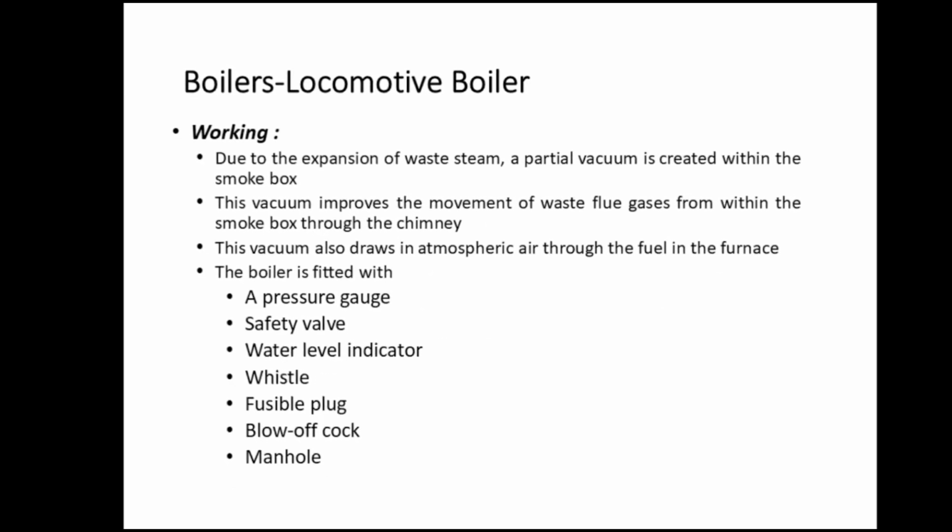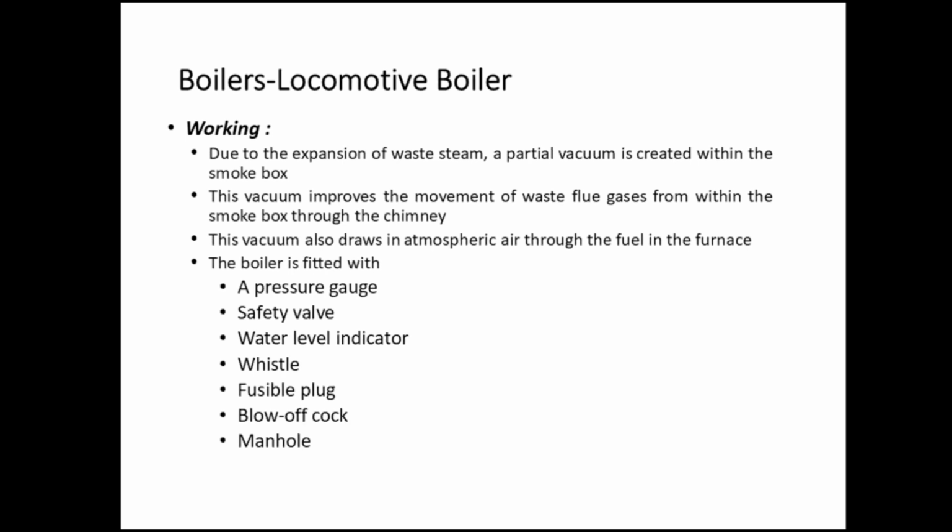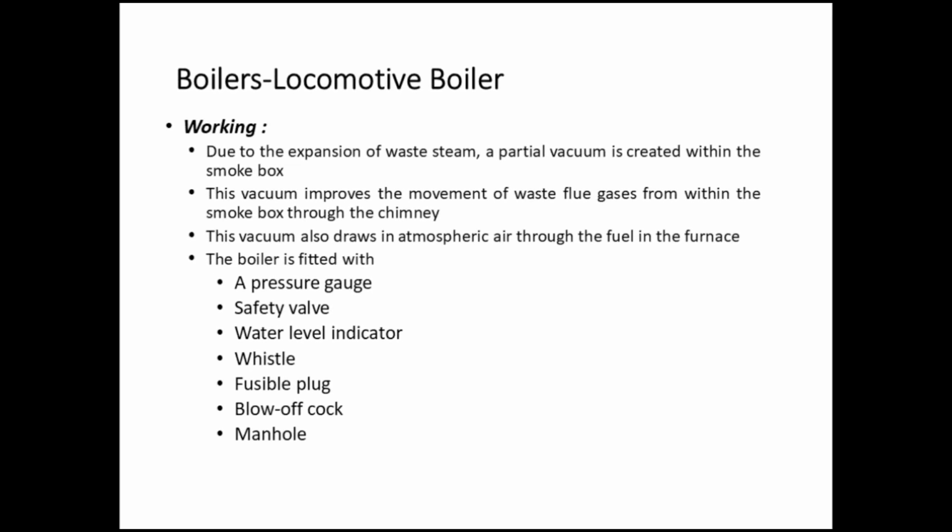Due to the expansion of waste steam, a partial vacuum is created within the smoke box. This vacuum improves the movement of waste flue gases from within the smoke box through the chimney. This vacuum also draws in atmospheric air through the fuel in the furnace. The boiler is fitted with a pressure gauge, safety valve, water level indicator, whistle, fusible plug, blow off cock, and manhole.